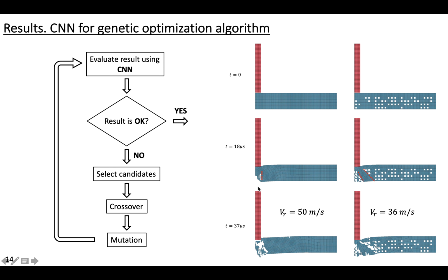splitting this single vertical crack for the solid target into 2 inclined cracks, which generate a big fragment which consumes momentum from the projectile and slows it down. This is the common feature for all these optimized perforation patterns: just to generate a large piece that would consume momentum from the projectile.